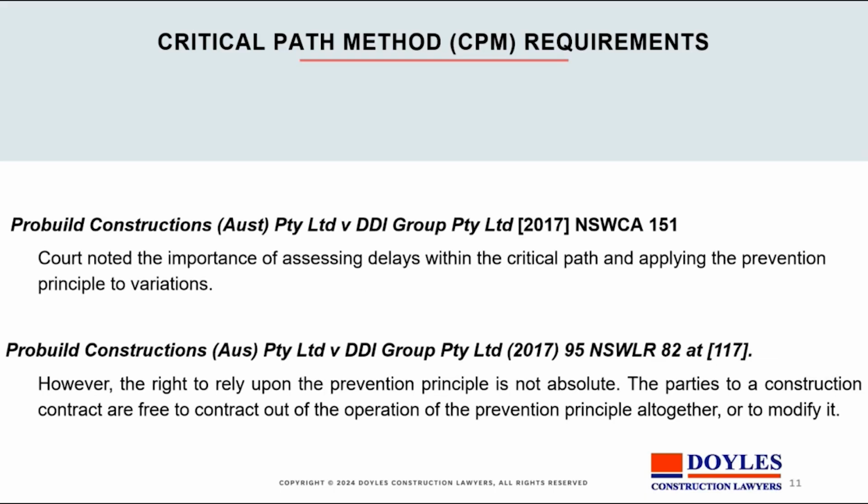There are a couple of cases where that was considered as important, and they've got Pro-Bill there, which is the importance of assessing delays within the critical path and then applying the prevention principle to variations. So there the court said, well, you've got to look at the critical path, but then again, if you vary the work on the critical path, one could expect to cop an EOT claim, probably with costs.